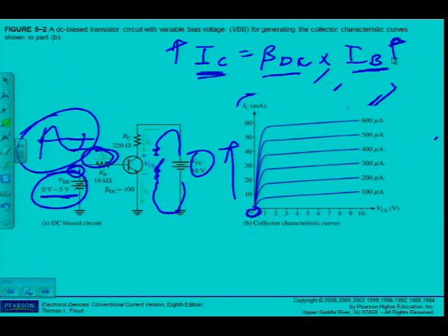Say for instance now, remember that we had our load line there. There's my load line. I know I have to stay between the cutoff and saturation points. Let's say I use 300. It gives me a Q point more or less in the middle of the load line. There's my Q point. So I'm going to start there applying my signal.